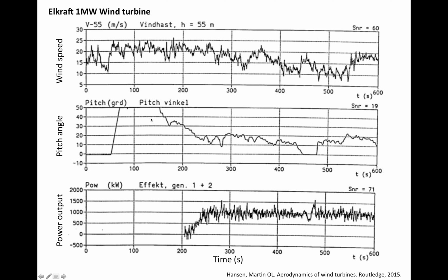The reason that the pitch angle curve is a lot smoother than the wind velocity curve is that adjusting the pitch angle mechanically, using either an electrical motor or hydraulic valves, is actually a lot slower than the rapid fluctuations in the wind speed. So under turbulent wind conditions, it's a very demanding task to keep adjusting the pitch to the most appropriate angle under high loads.